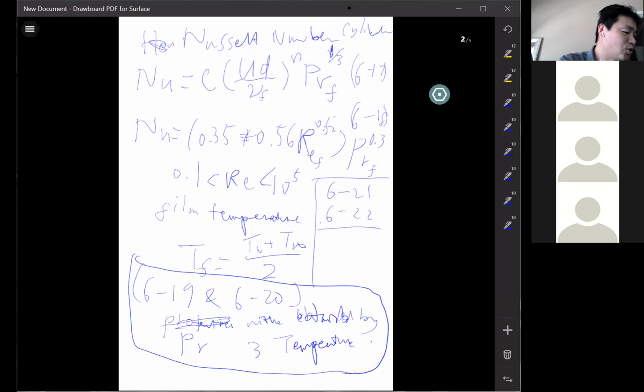There's also 6.23, 6.24. I don't think that's too many equations. They have different Reynolds number ranges, so you can pick one. And the sphere also presents you so many equations for the heat transfer Nusselt number. Usually we just use the last one, 6.30. It serves a good Reynolds number range and a good Prandtl number range. And from my knowledge, it's commonly accepted. It has high accuracy.